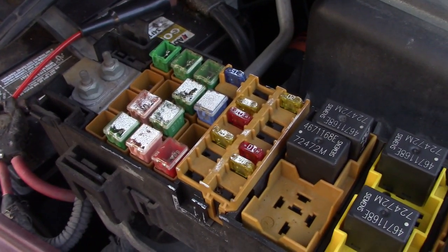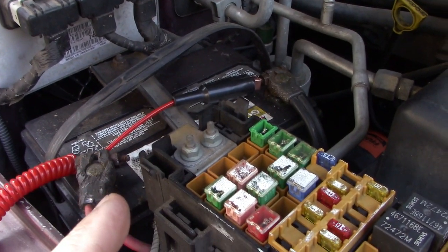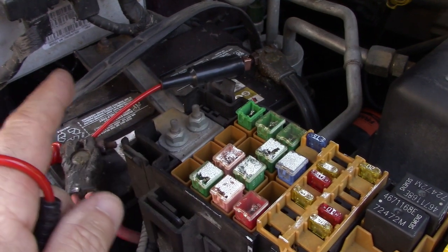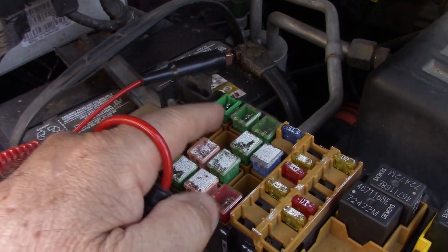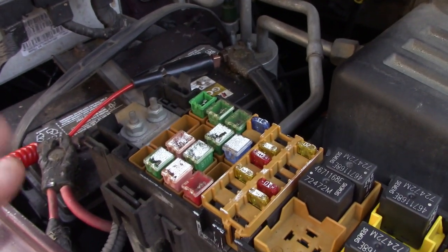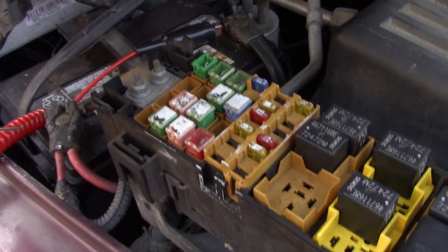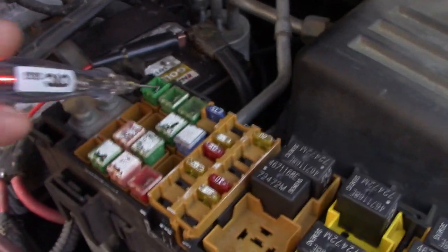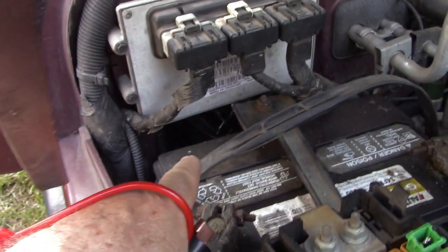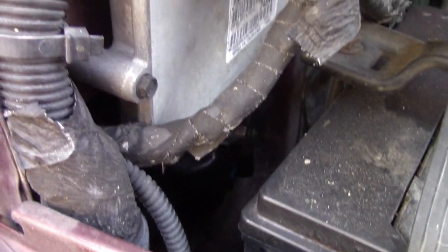So if we get inside and test it at the blower motor relay, and we don't have any power, then we have to figure out where we lose it between there and here. Okay, that's how it works: once you lose power, you backtrack and find out what exact point you're losing power, and then address that issue. But we know that we have power at this fuse, and then the blower motor is in behind the battery. If you can't see it, trust me, it's back there.